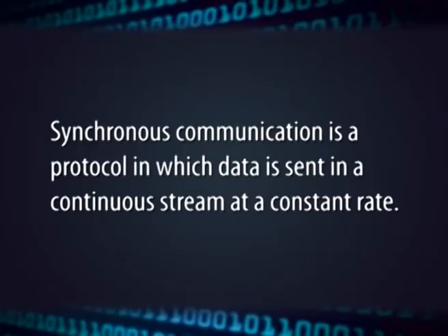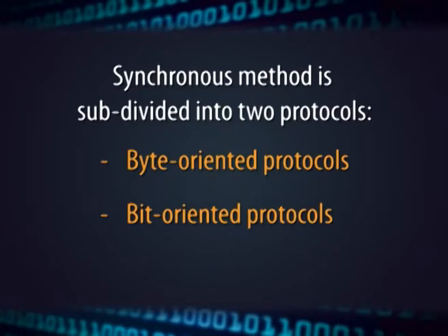Synchronous communication is a protocol in which data is sent in a continuous stream at a constant rate. In modern circuits, it is wasteful to dedicate one wire or channel solely for the transmitter's clock. Hence, currently receivers have a local oscillator called the receive clock, which is synchronized to the transmit clock by special techniques by watching over the data pattern. The synchronous method is further subdivided into two protocols. Byte oriented protocols.